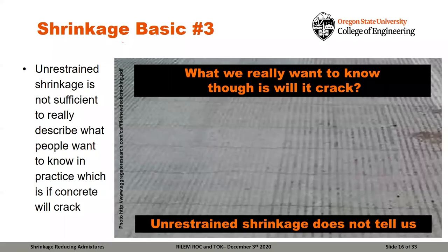Now, the third basic item that we wanted to really talk about with shrinkage is we often talk about the free shrinkage of our concrete. How much does it shrink if it's not restrained? However, this really isn't enough to describe what people really want to know in practice, which is will the concrete crack when it's placed into our structure?